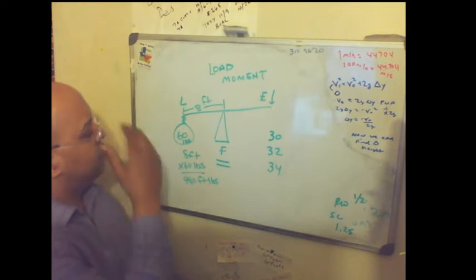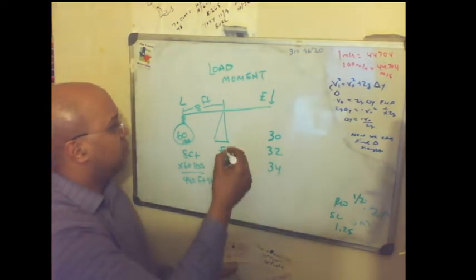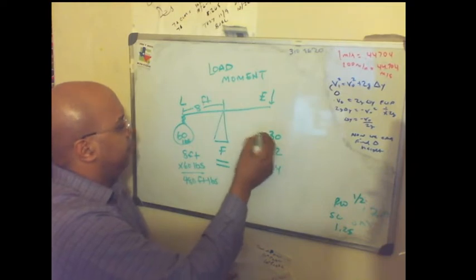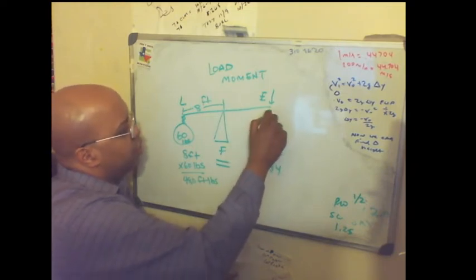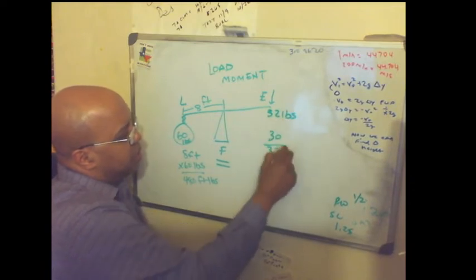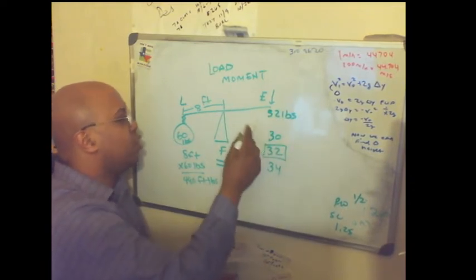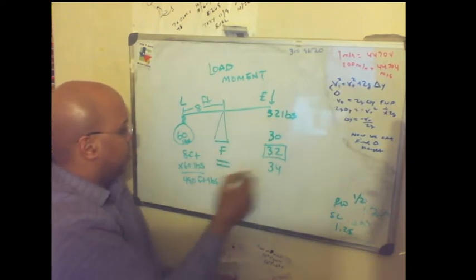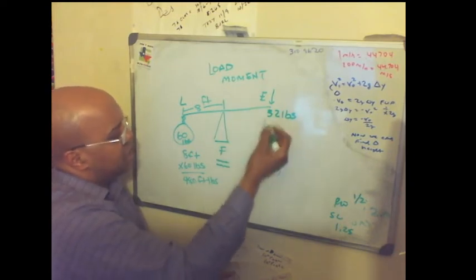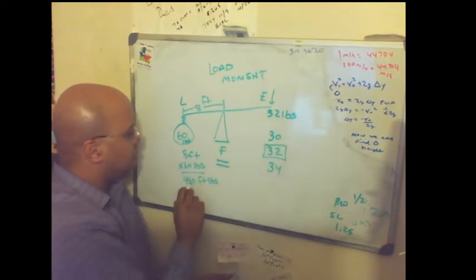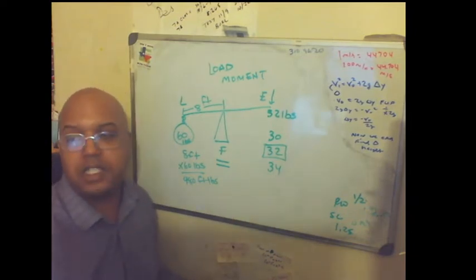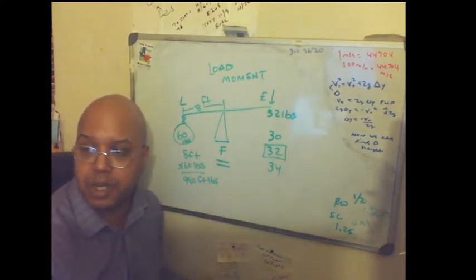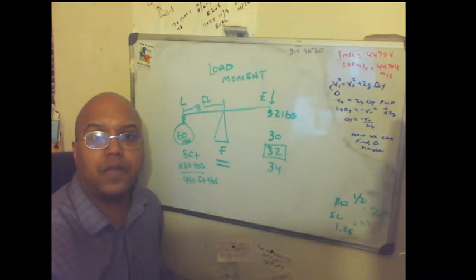So, anyways, if we're going to use 32 pounds, which it looks like you made that answer in your book, the distance must be such that you multiply that distance by the pounds and come up with 480 foot-pounds. So just for speed purposes, because I know this is a little bit of a lengthy explanation, 480 divided by 32.